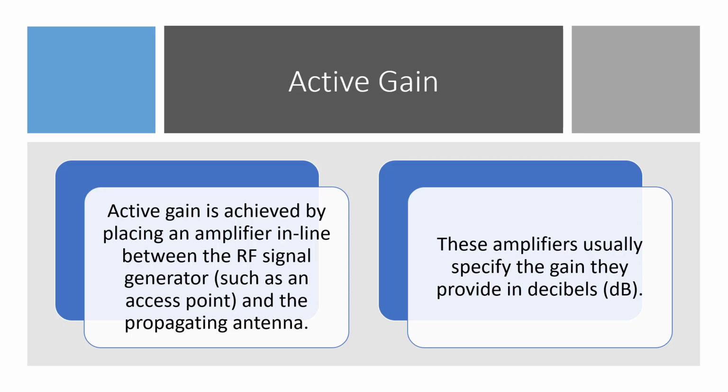In the digital domain, they are called store and forward amplifiers, where the incoming signal is processed and stored so that the actual bits are recovered. Then these bits are retransmitted. So it doesn't work in the analog domain, amplifying whatever signal comes in.